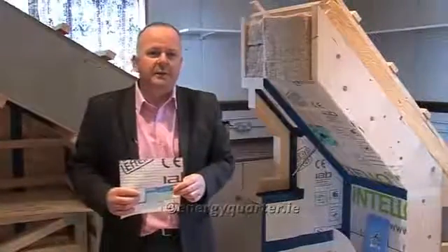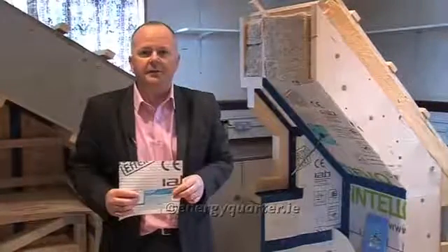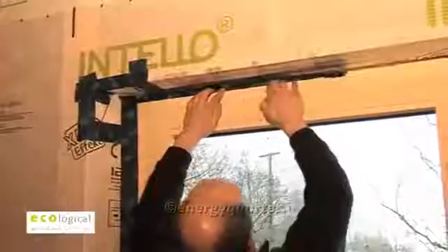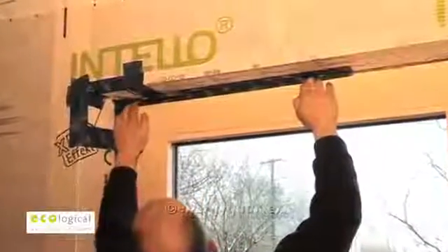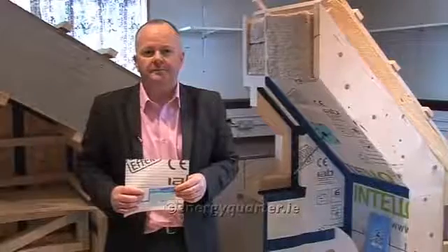So you might think, well, why build our houses to an airtight standard? Well, the first obvious benefit is that it cuts out any drafts. So all the junctions around windows, any floor to wall junctions and so forth are completely draft free. So we don't have any uncontrolled cold air infiltration.